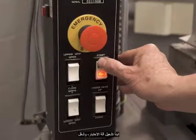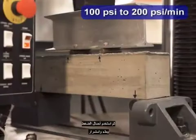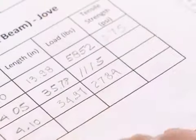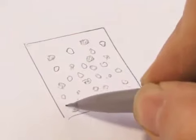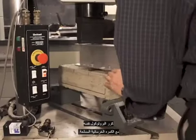Turn on the testing machine and activate the software to read load and deformations. Next, apply the compressive load slowly and continuously until the specimen fails. Record the maximum applied load. Finally, examine the fracture surface and estimate the percentage of aggregate that has fractured. Repeat the same protocol for the reinforced concrete beam.